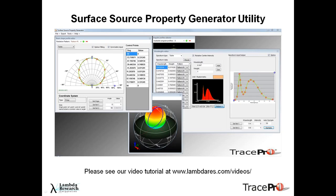And then when we finish that up, we can see some of our results here, and we can actually get an estimate of the CCT, correlated color temperature, and the color rendering index. So we can get a feel for the source even before we've done anything with it. And then we can export that over to TracePro, and it'll insert that right into your Surface Source Property catalog database in TracePro, so you can use that with any of your models in the future. I should note, if you go to our videos section off of our homepage, we do have a couple tutorials on using this utility, some step-by-step videos.